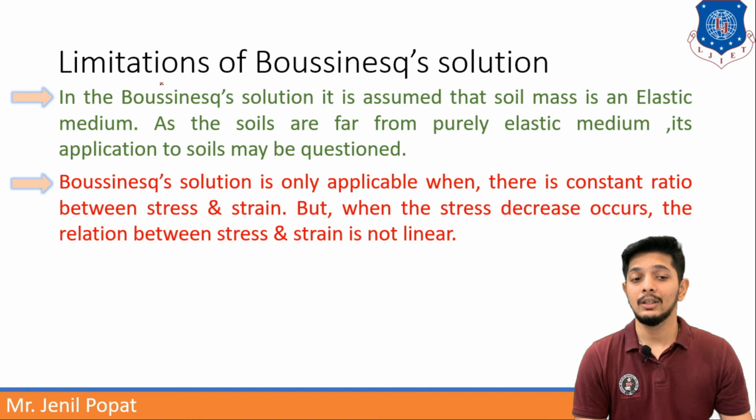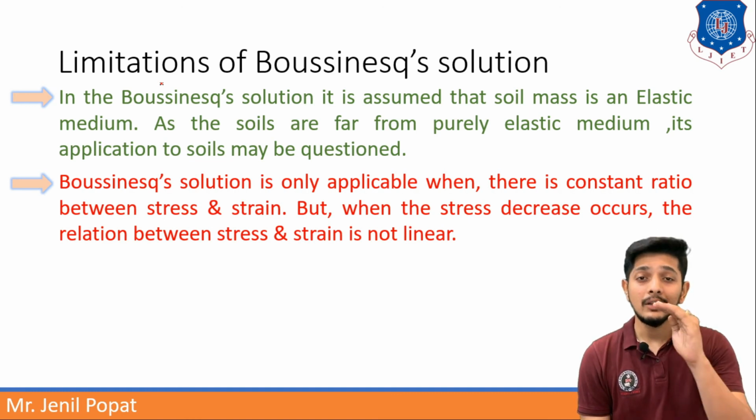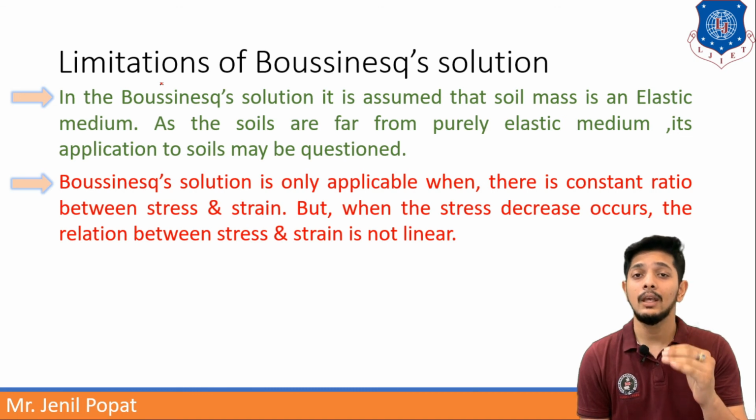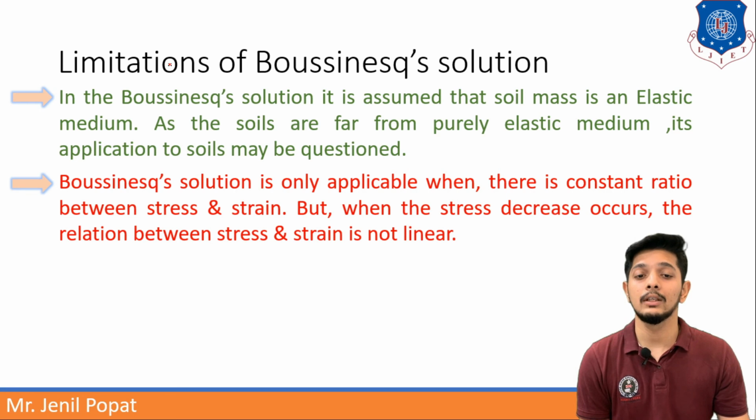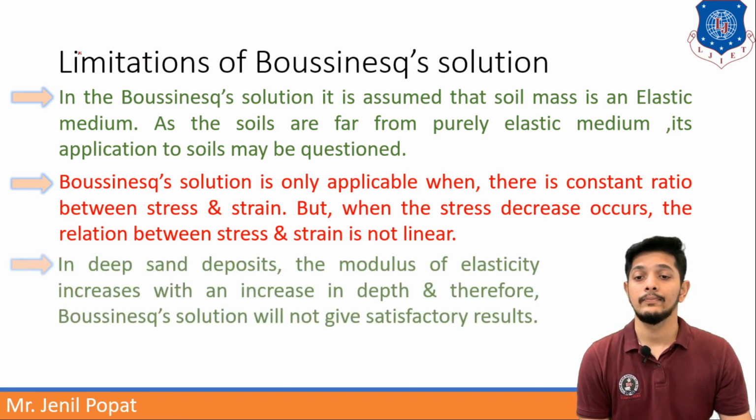But when the stress is decreasing, the stress and strain will not be elastic in the actual field, so we can question that. In deep sand deposits, the modulus of elasticity increases with an increase in depth, and therefore the Boussinesq solution will not be applicable in deep sand deposits. So these are the limitations of this theory.